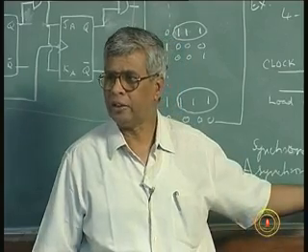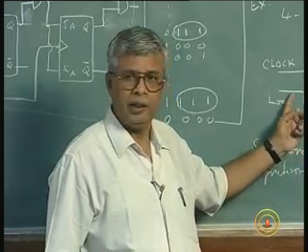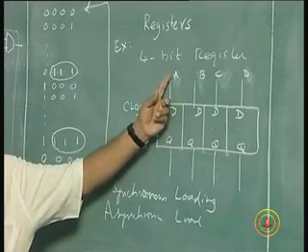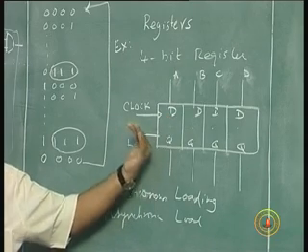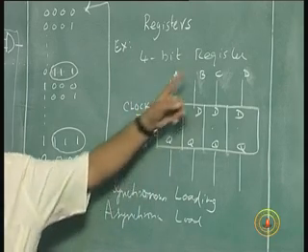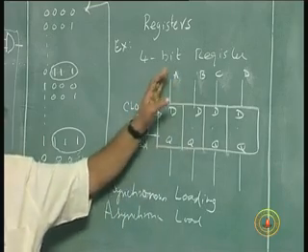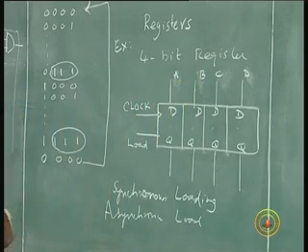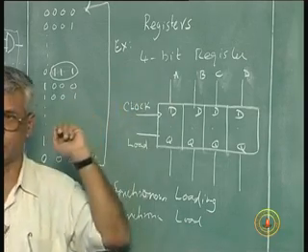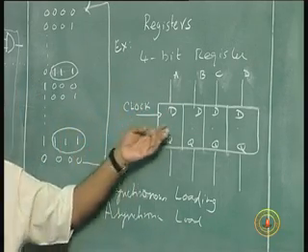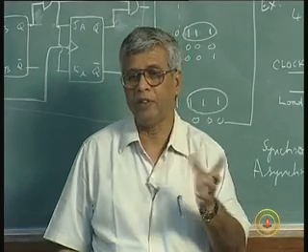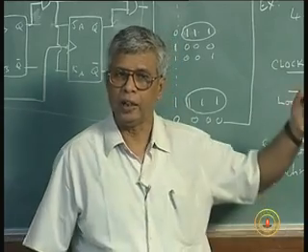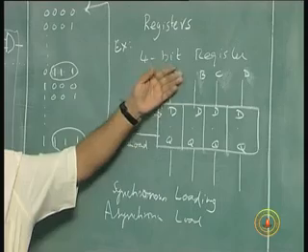Now, if I have this load control, I can put this load at the time when this data was available and remove this load pulse, and then the clock may come and go, but the new junk value cannot enter in. Even though you do not have the original values, the arbitrary random values that ABCD assume do not get into the flip flops until another load pulse comes. So, after reading the data after 100 microseconds, I can put one more load pulse and capture one more set of data.